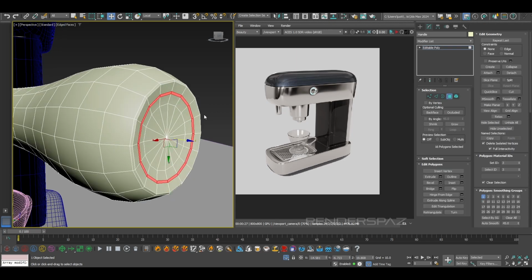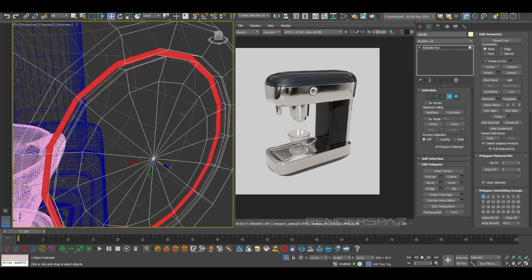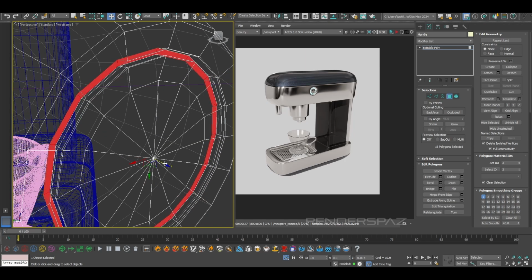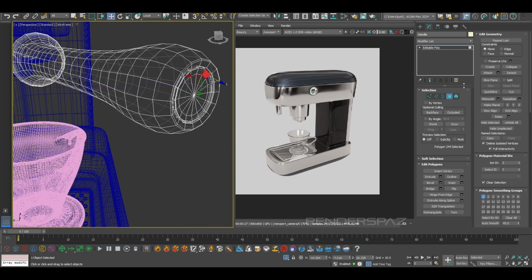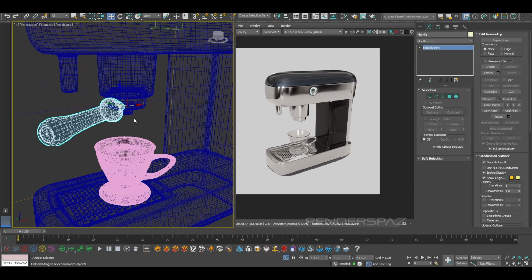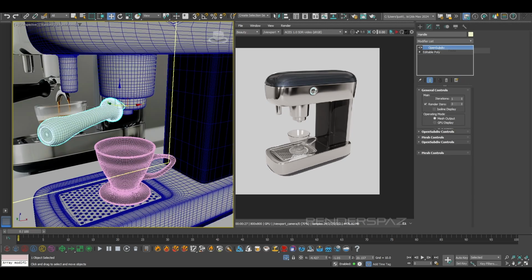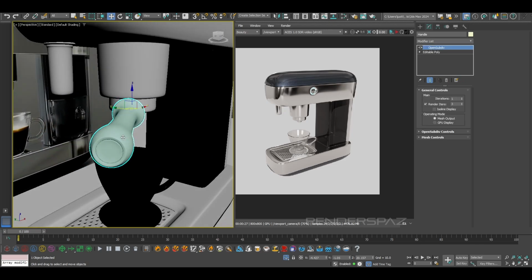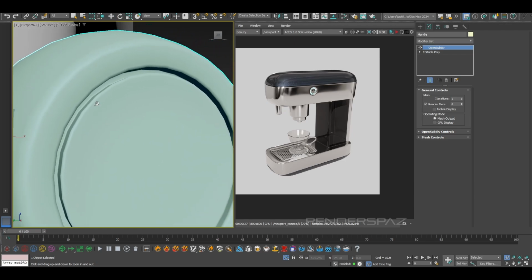Ring, control, click on face mode, hold shift, drag one, hold shift again, drag again, and hold shift one more time to get that additional edge down there. That makes sense. So you're going to have the 2 and 2, because that way when you add in your open subdivision, you'll see what happens here. You get this kind of details in there, right? So you get that little extra edge in there.